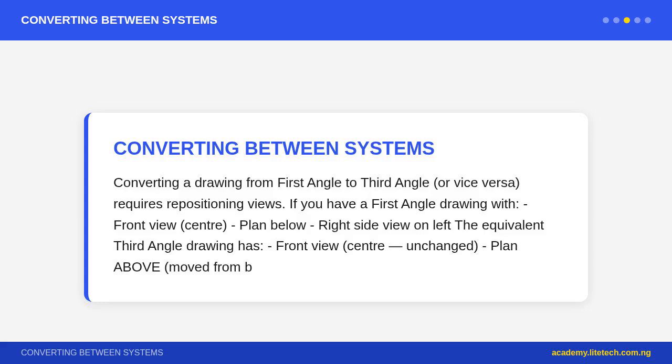Plan: above front view, rectangle 60 by 40 mm with a dashed rectangle in the top right section showing the hidden step, 20 by 40 mm, dashed because it is below the top surface, visible in front view but represents a ledge in the plan.